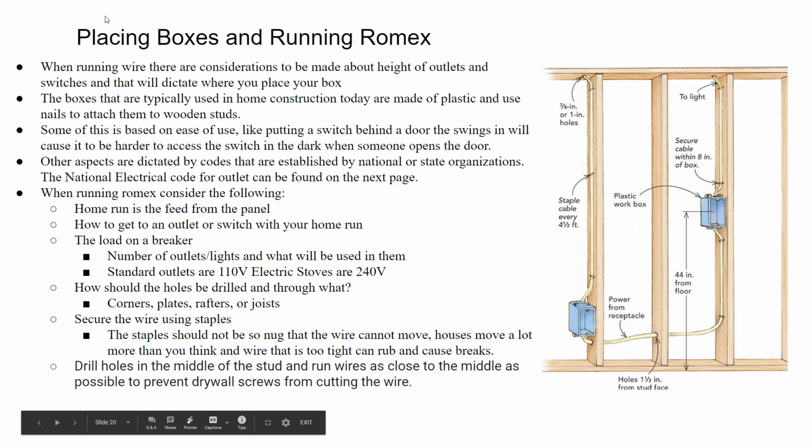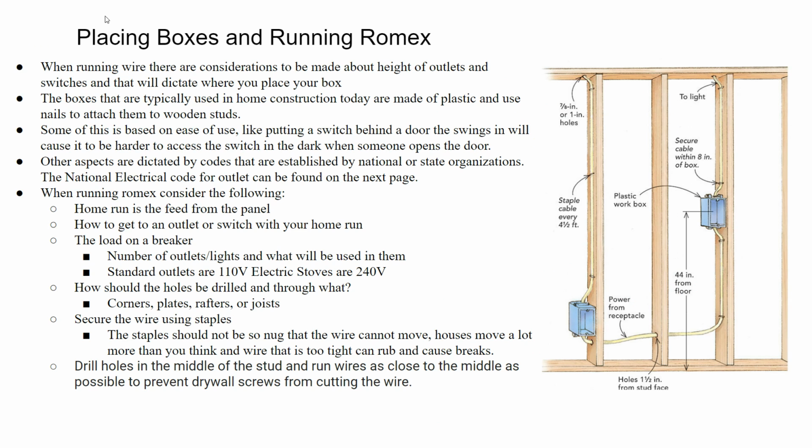So where does this stuff go? First off, it's run in your wall. You try to avoid putting stuff on the outside part of the wall. So what we want to do is place boxes. And those are the only place we will mate wires.